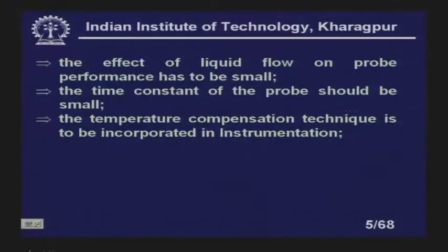So, we should not give much emphasis to the time response. But sometimes we have to take some action. Suppose the dissolved oxygen concentration or partial pressure of the oxygen suddenly falls, so immediate action is to be taken. In that type of situation, a lower time constant or fast response of the sensor is always helpful for taking action.